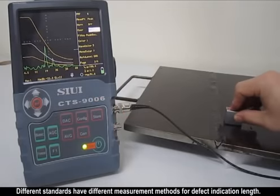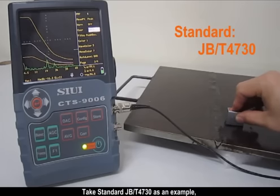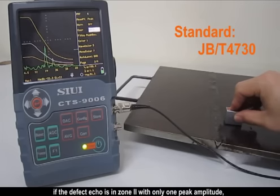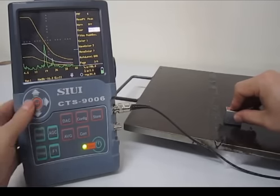Different standards have different measurement methods for defect indication length. Take standard JB/T 4730 as an example. If the defect echo is in zone 2 with only one peak amplitude, we can use the 6 dB method to measure indication length.